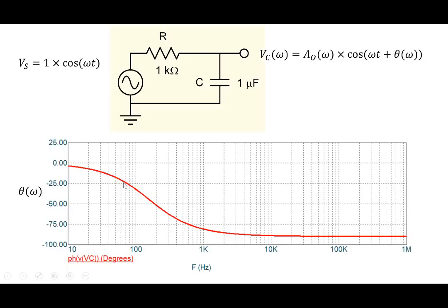But as the frequency increases, the amplitude also decreases, and the phase starts getting different here. The phase starts becoming negative here. Okay. So what we are saying is, you can understand linear circuits. In fact, you can obtain complete information about a linear circuit if you excite them through a sinusoid, and you look at the magnitude of the output voltage as a function of frequency, and you look at the phase as a function of frequency, and you'll be able to understand that particular circuit, what its function is, and then that would help you understand and design those particular circuits for different applications that are there.